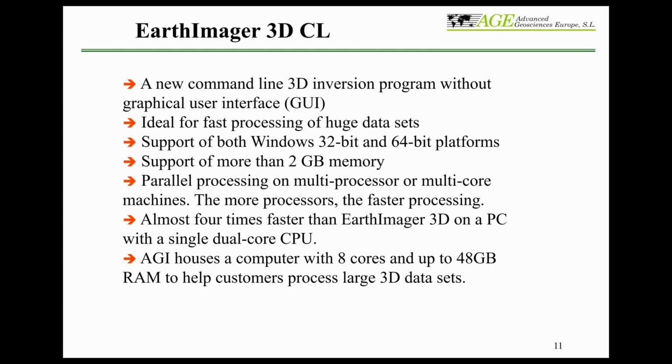Sometimes, let's say, if you do many lines, combine those many lines, and at the end you end up with maybe 500 or 1,000 electrode locations and maybe 50,000, 100,000 data points, you can do that also in EarthImager 3D in the Windows graphic interface, but it may take some time. Sometimes it takes hours, sometimes more than half a day or 1 day. In that case, you may need to just run your software overnight and see the next day.